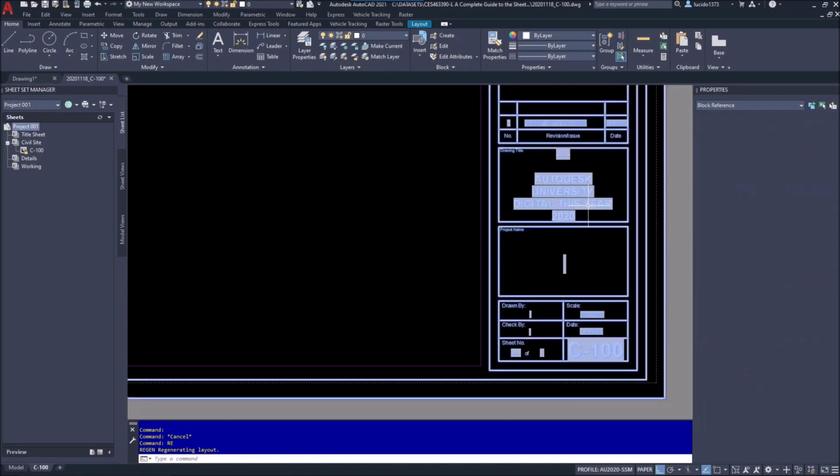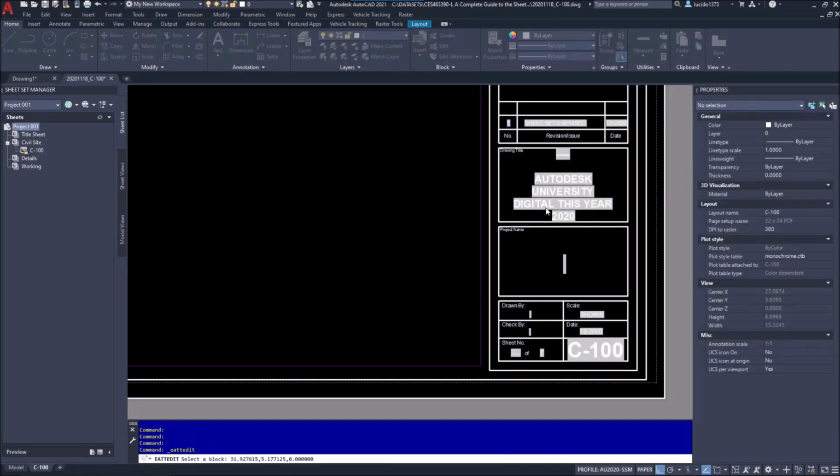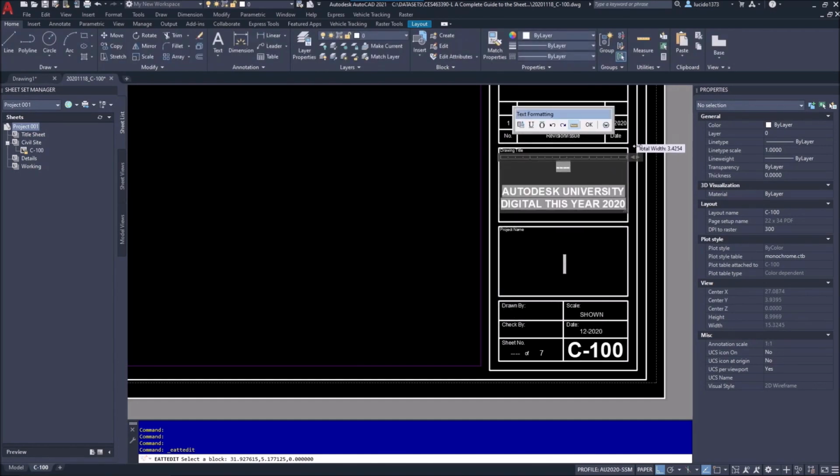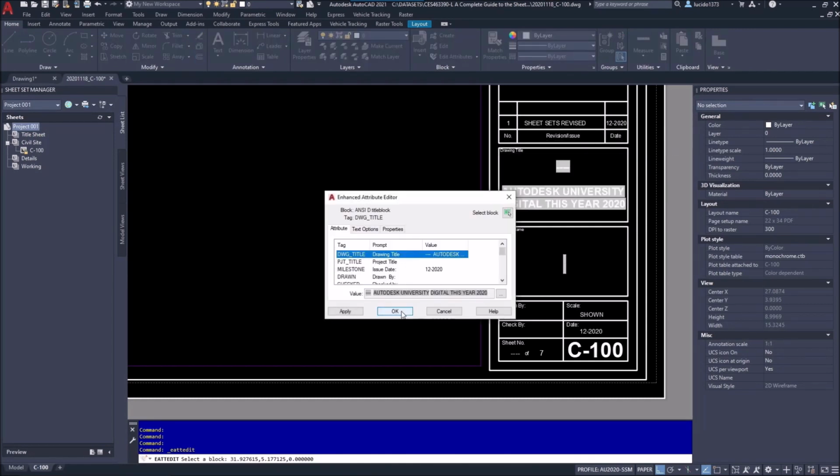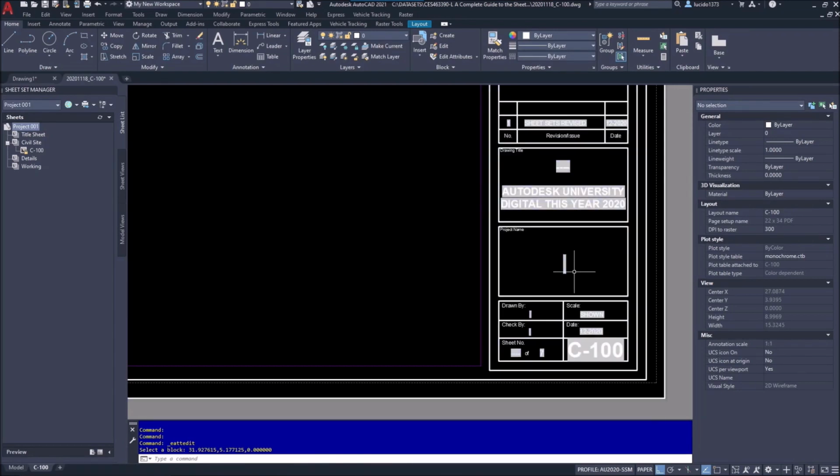And if you get that in your MText, you can actually define the width of the MText by double clicking it and going into here. And you can change it. It can't be locked if that comes up as a question, but a lot of people like using DText because of that factor of that changing, but you can manipulate it there.